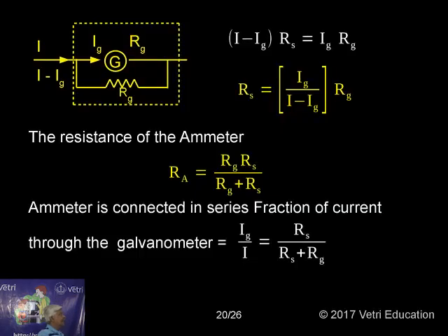So I have given a circuit diagram. This is a moving coil galvanometer. The galvanometer is a more sensitive instrument, so I bypass it with a resistor here. So this is not Rg, kindly correct it, it is Rs. I consider the resistor in parallel, and that is called the shunt resistor.